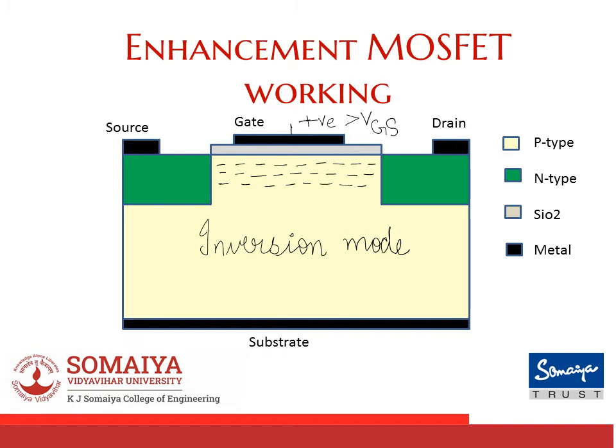Since you have negative charge carriers building up in the channel, this mode is going to be called inversion mode. As VGS increases, my current ID will also increase because the width of the channel will increase, so the number of charge carriers that will move from source to drain will also increase.